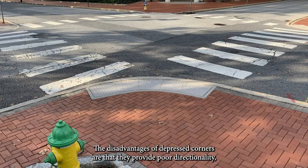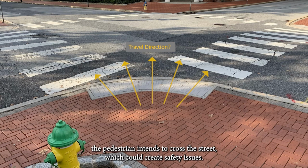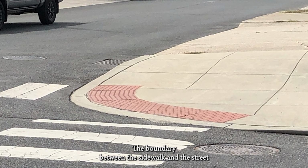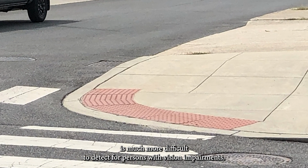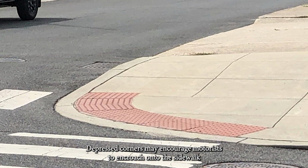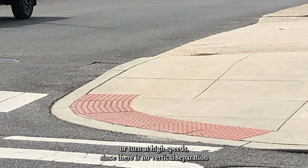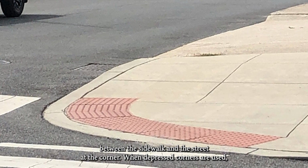The disadvantages of depressed corners are that they provide poor directionality. And like diagonal curb ramps, it's difficult for motorists to determine the direction the pedestrian intends to cross the street, which could create safety issues. The boundary between the sidewalk and the street is much more difficult to detect for persons with vision impairments. Depressed corners may encourage motorists to encroach onto the sidewalk or turn at high speeds since there is no vertical separation between the sidewalk and the street at the corner.